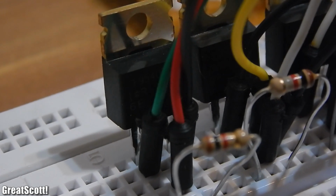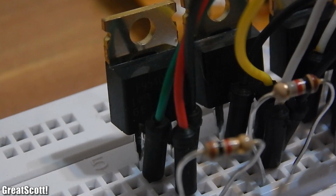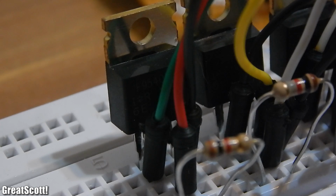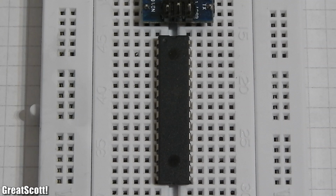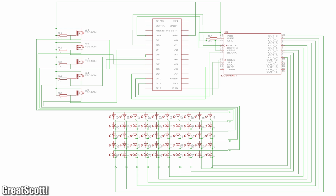But one row can draw up to 200 milliamps with 10 LEDs, so we cannot connect those to one I/O. We have to use a P-channel MOSFET as a switch. I'm using the F9540N and connect gate to my I/O, source to 5 volts and drain to the anode rows. And I use 10 outputs of my TLC5940 for the 10 cathode columns. You can take a look at my schematic to get all the connections right.